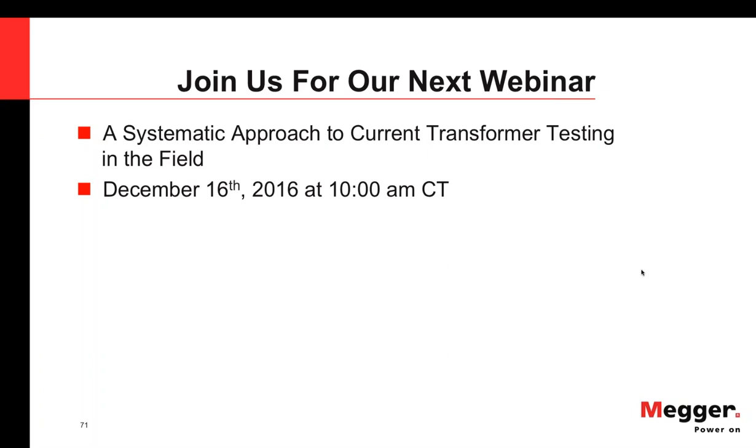And by the way, that's typically where you see that signature of third, fifth, and seventh, where the third will be the highest, then the fifth and the seventh. That pretty much shows you that you're having those types of loads.